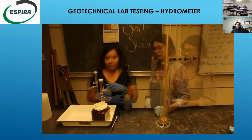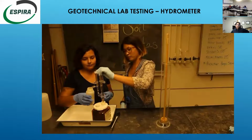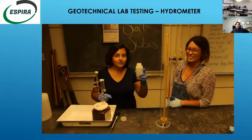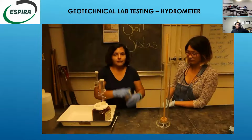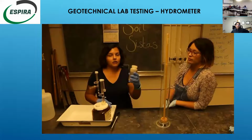So here we'll add 25 mils of SHMP. And now we're going to add 100 milliliters of water to this jar. So in here we have our soil, the SHMP, and 100 milliliters of water.